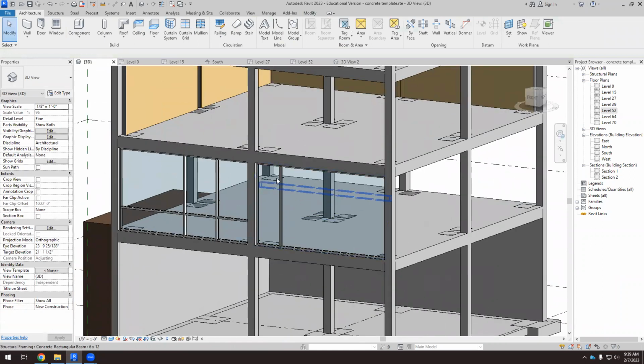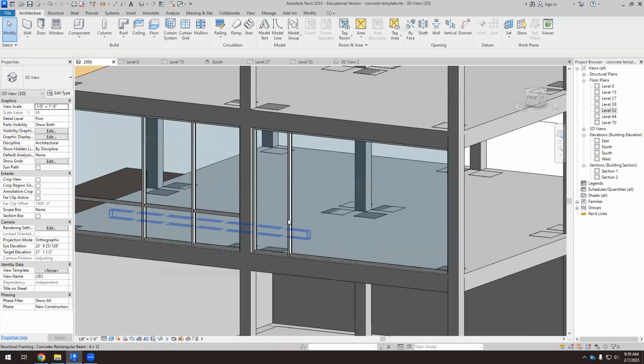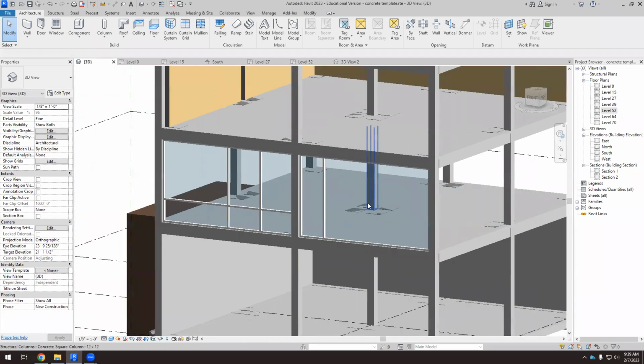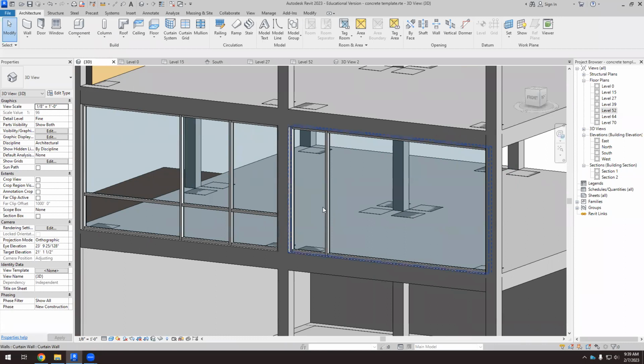If we have a vertical one, then here we can open the door between these two. This will be too big, okay? So we need more partitions there. But if we want to create the door here, the thing is that when we are working with curtain walls,